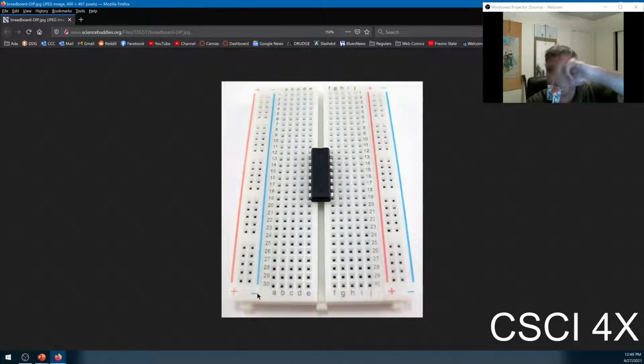So you have one wire coming in like this, the other wire is attached somewhere else. And then you get another wire and click it into E30. Those two wires are now connected. And so rather than needing to glue two wires together, you just put one wire into B30, you put another wire into E30, and then because there's a copper backplate running beneath them, they're now electrically connected, and current will flow between them. And so it allows you to very quickly prototype and click things in and pull things out.